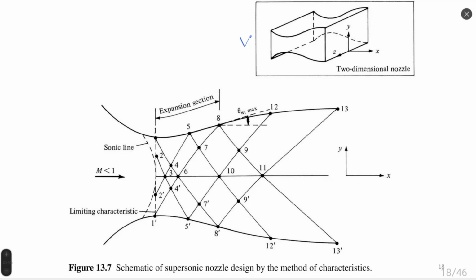There are several engines working in such geometry, planar nozzles. They have some advantages with respect to axisymmetric nozzles when we have a limited thickness of a body. For example, if it should be installed on an airplane, a low profile airplane, then planar nozzles can be a better option than axisymmetric rotational nozzles.